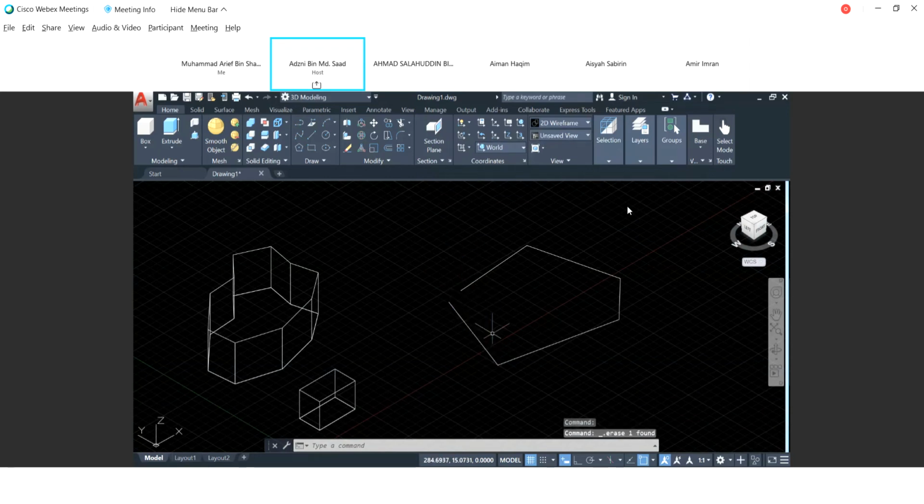The same thing goes here. This is one of the mistakes that a lot of students still make. Even though you have an enclosed geometry like this, when you press pull here, you can see it says select object or bounded area. If you move your cursor in between all these lines, it's going to highlight all the lines. But you can also click on the line.